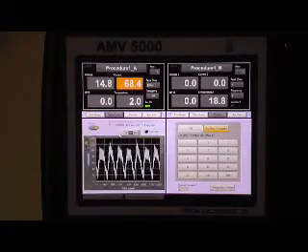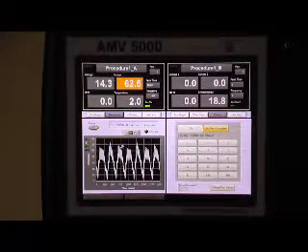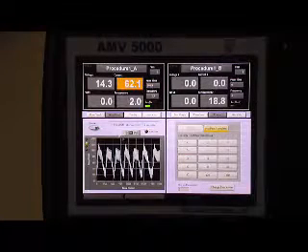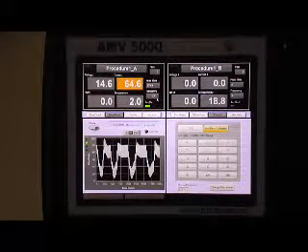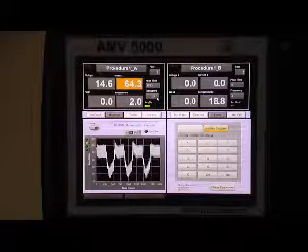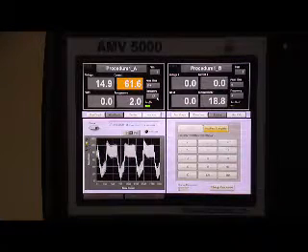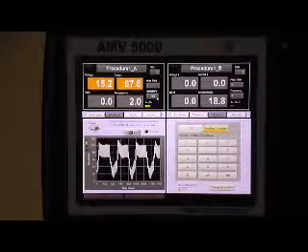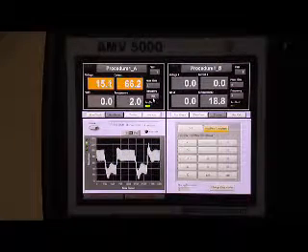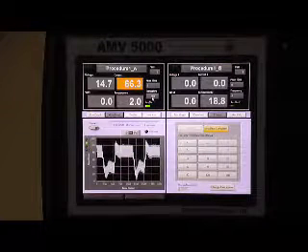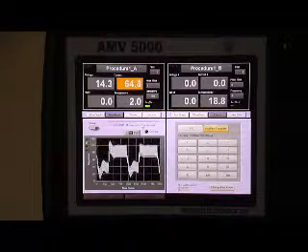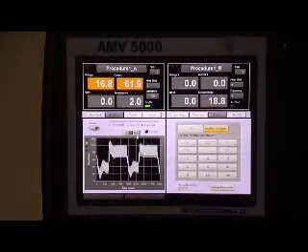If you have a particularly slow pulse period, we're unable to determine the exact frequency when it gets below about 1 Hertz. So as the frequency goes down, and it's just falling now, it's getting below the level that we can determine accurately with our frequency meter. But you can still analyze it by looking at the waveform graph.